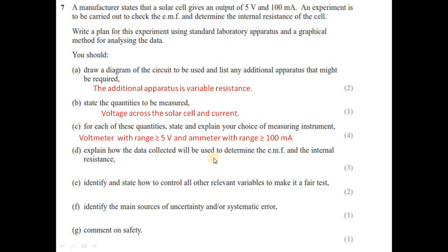Explain how the data collected will be used to determine the EMF and the internal resistance. In this case, because we have a data set for voltage and current, we are going to plot a graph between voltage and current.